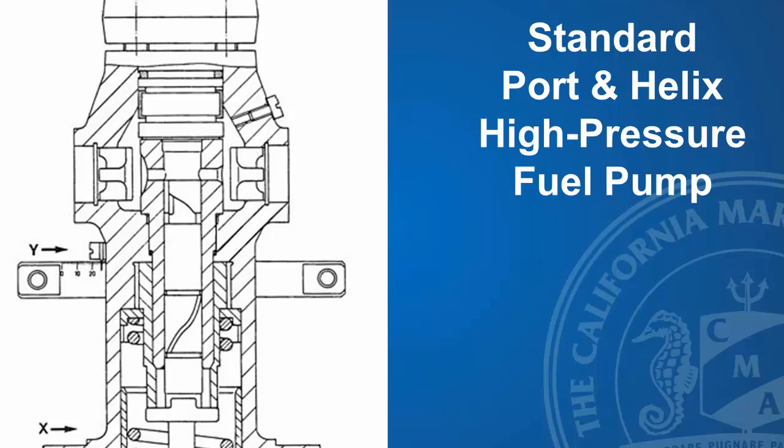On these high pressure pumps, injection pressures today are pretty typical between 1,000 and 2,000 bar. A bar is 1 atmosphere or 14.7 psi. So you're basically talking somewhere around, on average, about 25,000 psi injection pressures.